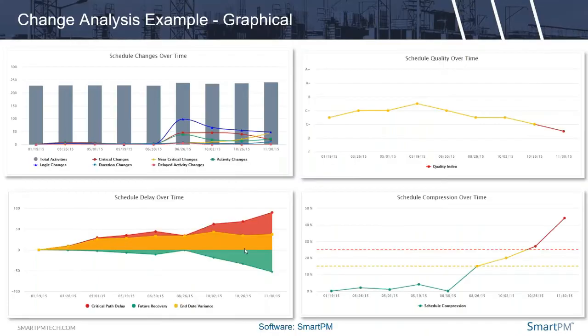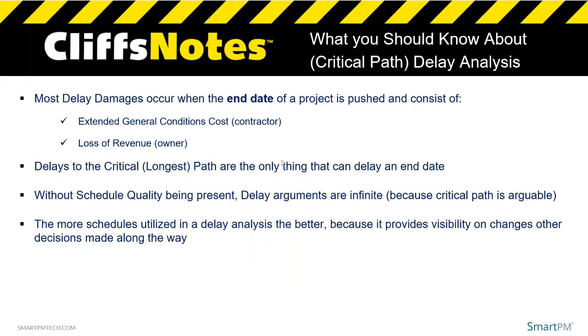And if an interim milestone is delayed 100 days, yet the end date's only kicked out 40, a lot of times people ask for those 100 days. But the reality is focus on the end date and the impact to the end date when studying delay. Now, understanding what actually delayed the job is more important. But let me get back to the other thing.